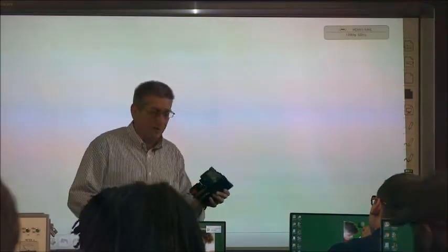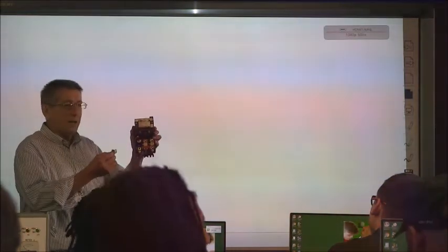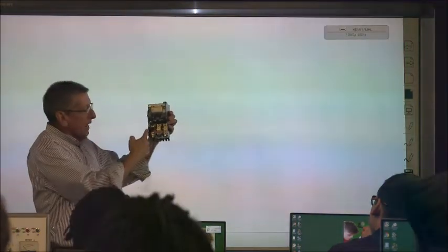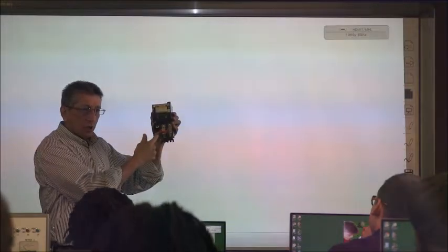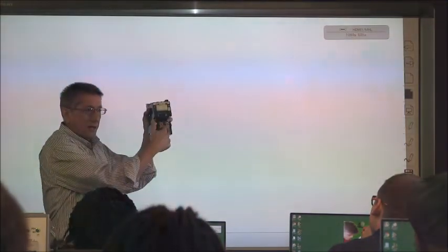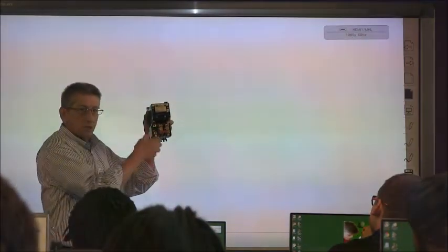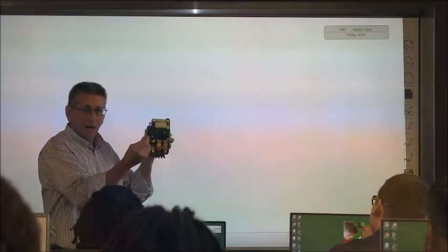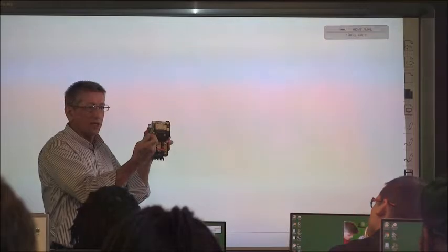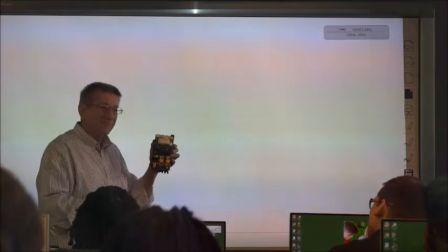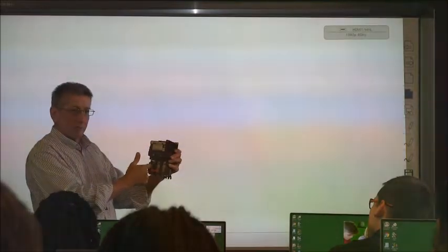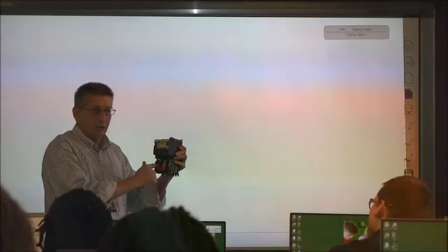Eutectic alloy. So yeah, you guys probably know how it works. What happens if one of the legs of the motor starts drawing too much current, it heats these up, right? It's going to heat whichever one up, it's going to trip. What happens is it melts the solder, or the eutectic alloy, inside this thing. There we go. And then it trips this little spring-loaded set of contacts in here.